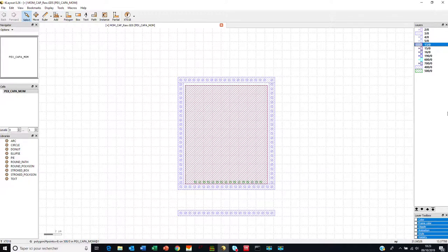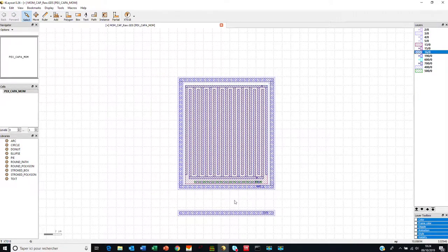Now another missing data is that we have metal in this structure, we have poly, we have lots of stuff, but in the actual IC, everywhere on the top of the silicon block, we have oxide that lies everywhere and that defines the capacitance values between all the nets. The trouble is that usually in IC design we do not draw the oxide.